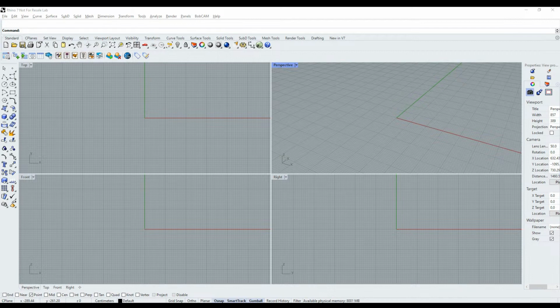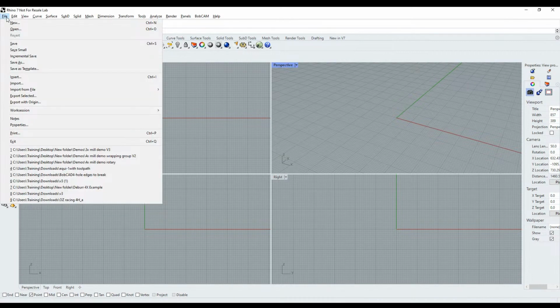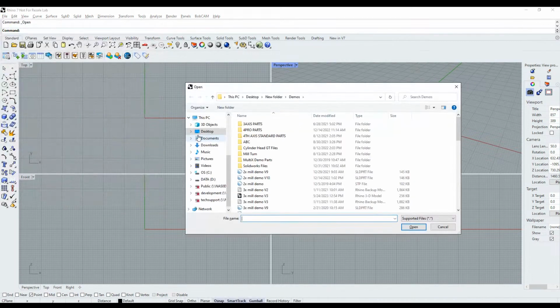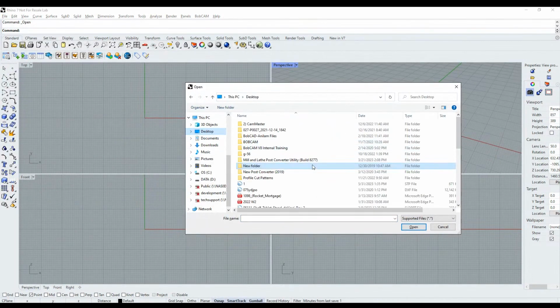Rhino has the capability of changing an STL file into a step file so that you'd be able to modify the model from there and make any changes that you need, any dimensions that need to be changed, things like that. So it can be really useful there, especially for 3D printing. I know a lot of people use STLs for 3D printers. So I'll go back to opening the step file here.